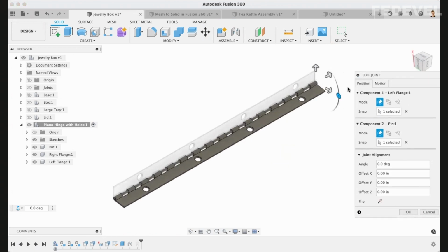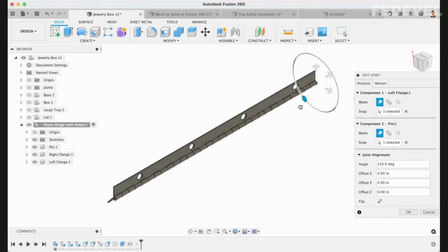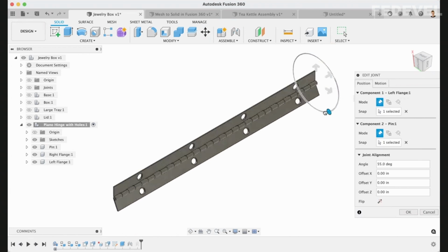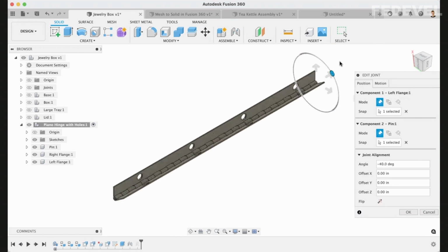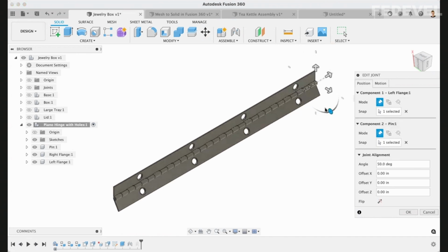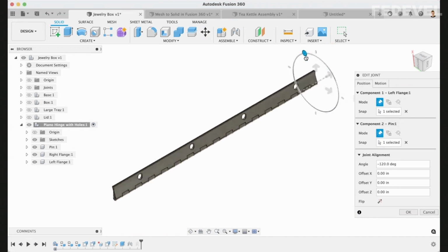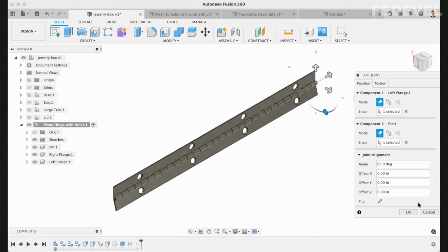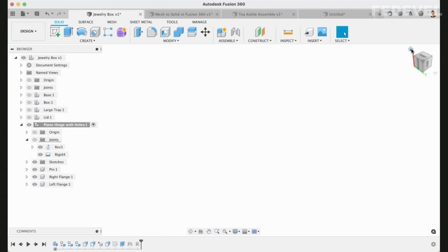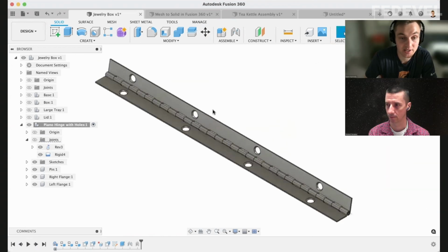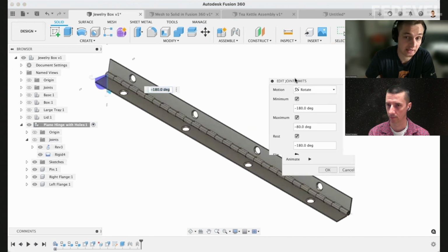If I go ahead and use this manipulator, you can see that based on how I apply the joint, this revolves around there. Now, one of the difficulties with this is that it isn't realistic for this to run into the other body. One of the solutions for that in Fusion is that whenever you set up a joint, we can go in here and create joint limits.